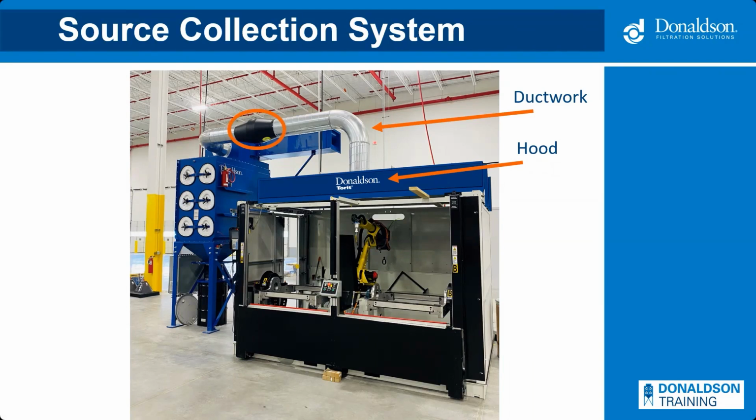Third, we can now select the correct style of collector determined by the type and amount of dust, such as the cartridge collector we choose for this particular system. And lastly, we can choose the fan. We now know the total air volume, and we can calculate the total resistance or static loss, another term we'll talk about a little bit more later today, of our engineered system. As stated before, if one component is poorly designed, the whole system is affected.